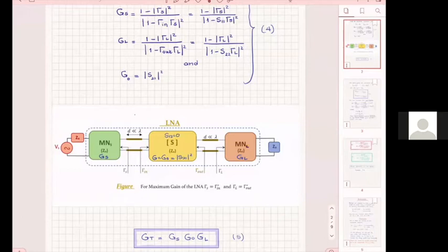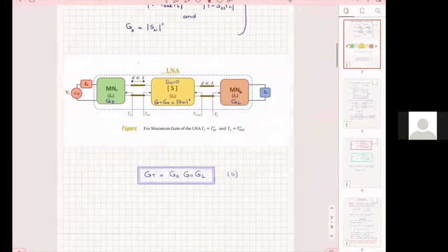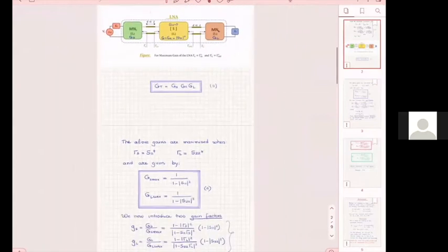And this is what is called the hybrid integration method. And then if you try to integrate lumps in the form we saw, like an MIM or a spiral inductor, they have a lot of problems with parasitic elements, especially at high frequencies, and never work very well. So there is always a trade-off whether you go for a transmission line or for lumped elements. Ideally, the lumped elements give you the best bandwidth, but transmission lines give you the least problems. So this is to keep in mind.